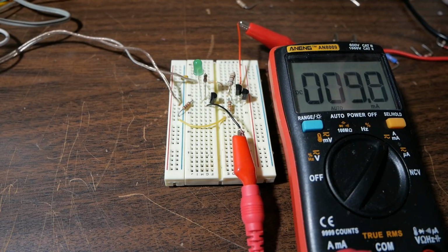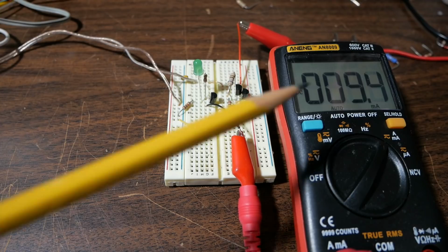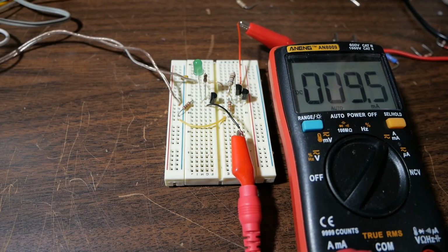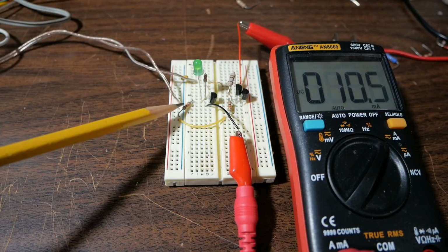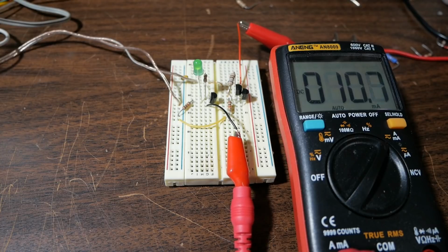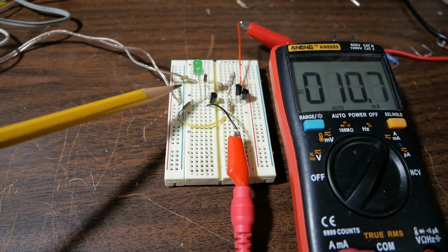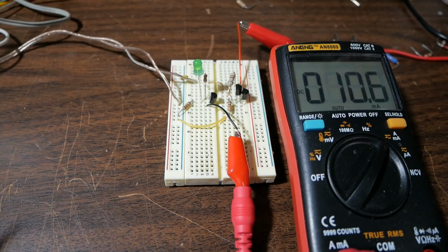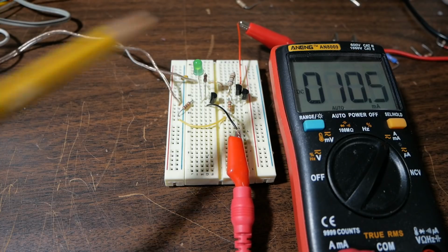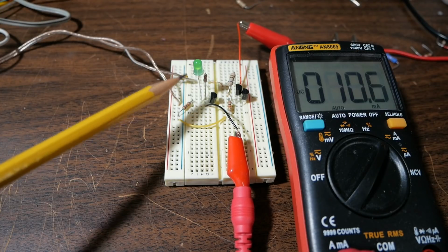Now it's running about 4 volts. You can see it's dropped 1 milliamp. So I really don't see a huge difference in the current going in here. The resistor I selected of 10K is plenty for this, so I think it'll work fine. It's not going to be an issue in the amplifier because the voltage it's being fed is not going to change much. It might change by a couple volts, so it's not really going to affect that. Plus it's going to be filtered.